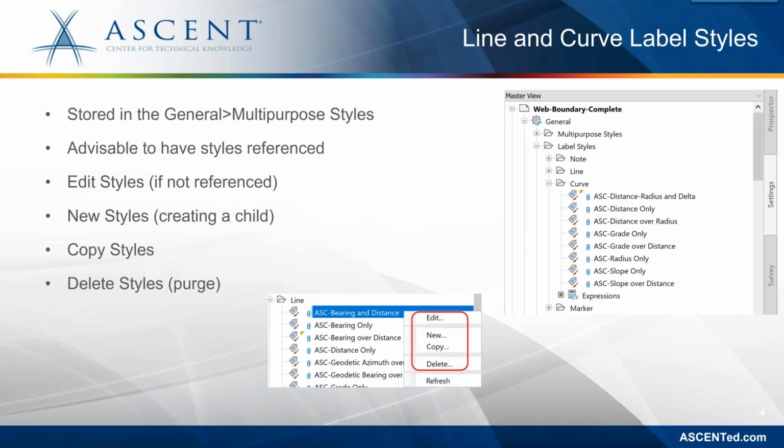The advantage is if you need to change a style company-wide or project-wide, you can edit it in that reference template and it will get pushed through to all of the drawings that have that style referenced. The disadvantage is I can't make any edits to those styles in my child drawing, in this particular drawing, because it's referenced from the template.